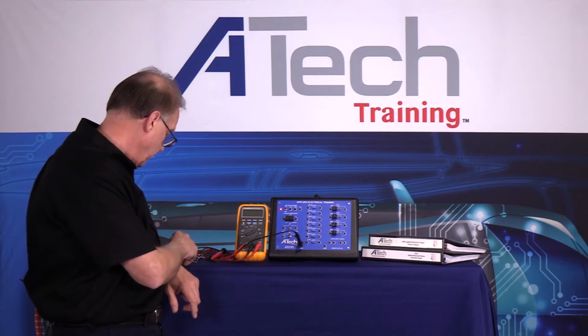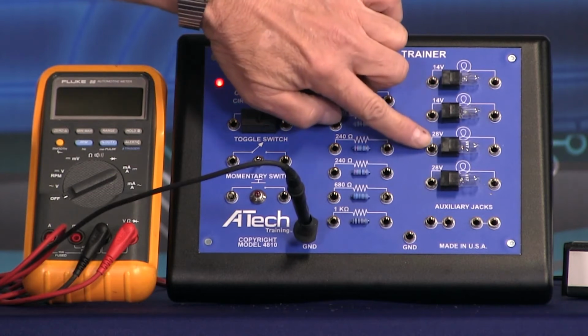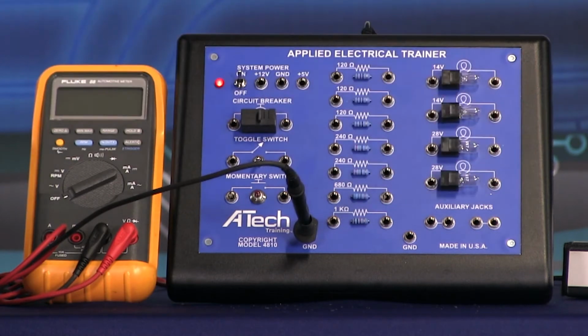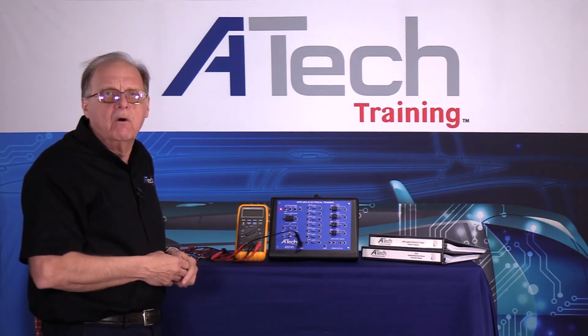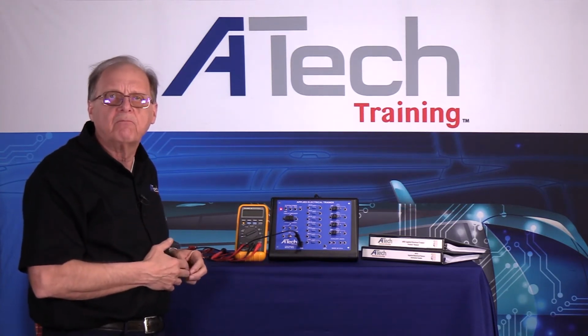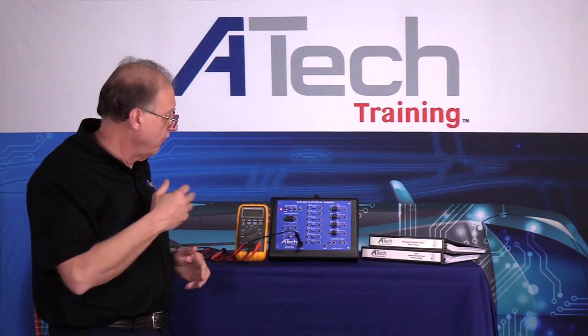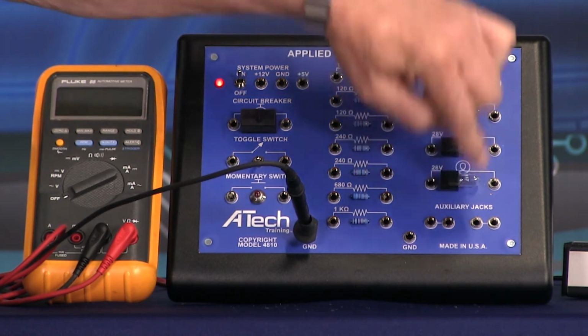Now, if I'm looking at the next side here, I have two 14-volt bulbs and two 28-volt bulbs, which are here and here, and then at the bottom I have the auxiliary jacks. And I told you about the auxiliary jacks. Those are things we can add on, like relays, or a solenoid. The big thing I like to do is check an EVAP solenoid sometimes and show them how it works, because it opens to allow flow and closes to stop flow. So there's a couple of things you can look at. Again, you have three different areas you can use: the controls on the left-hand side, the resistors in the middle, and then the loads on the right-hand side.